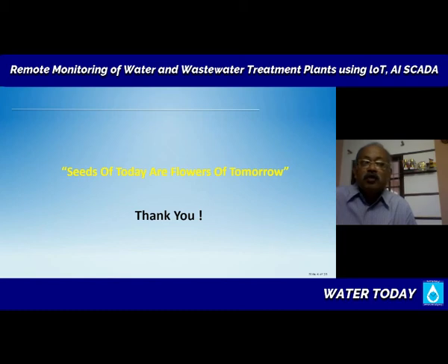So if you have the choice, then what I would recommend is you operate in batch mode of operation, where you set your time duration and you can have control over the timer. For example, you say that removal of sludge from a settlement tank, I want to remove for 10 minutes every half an hour. I'm just giving some random number. Now, it can be made available in your control room. So if you want to change this from 10 to 15, then you can change it.